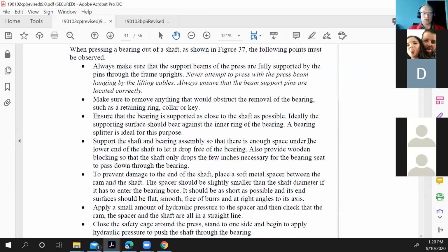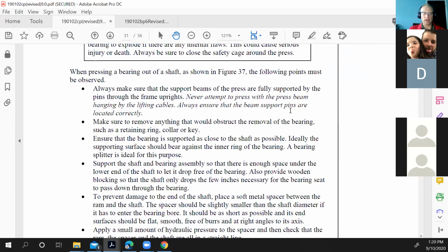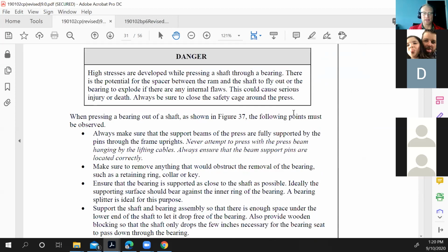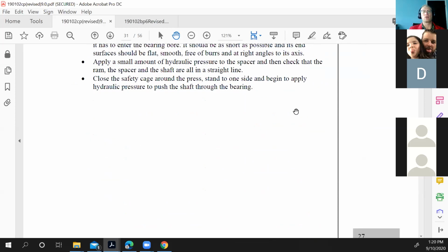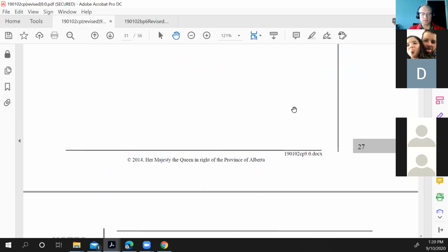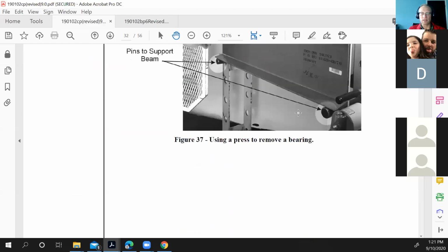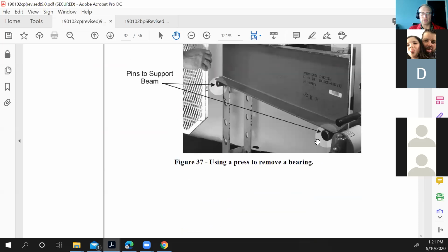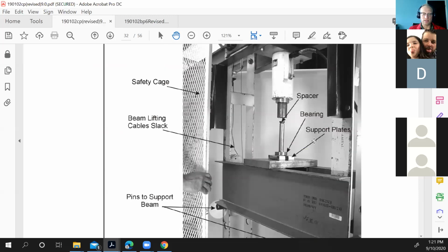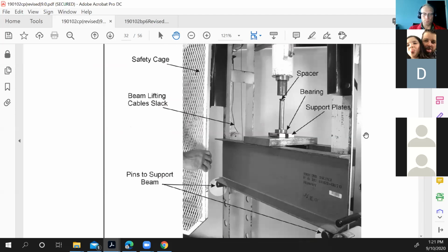So a couple of things. Read all of these dangers about a hydraulic press or an air press or whatever kind you may have. They can be very, very dangerous. And I have a good video about bearings coming apart in a press. They are very dangerous if that happens. The other danger about bearings is, yet again, I'll talk about it. It has to do with those thrust bearings, seal installers, and those coming apart as well, okay?